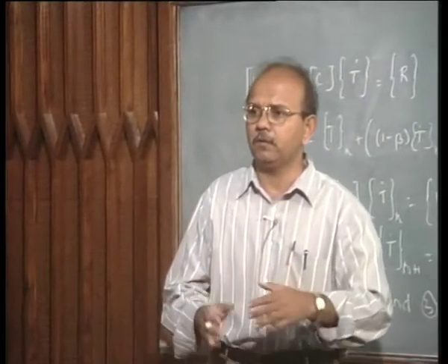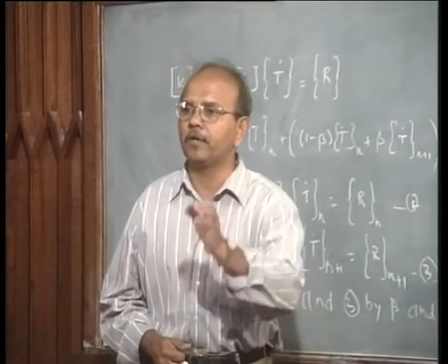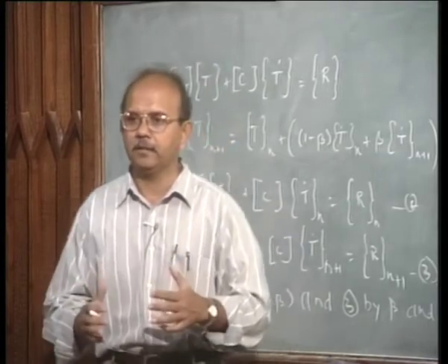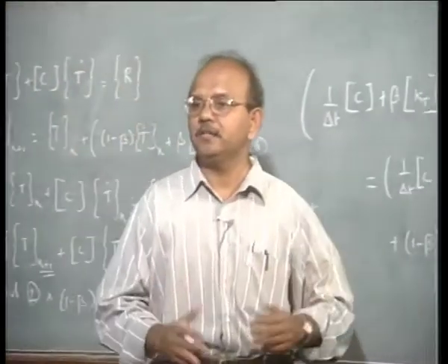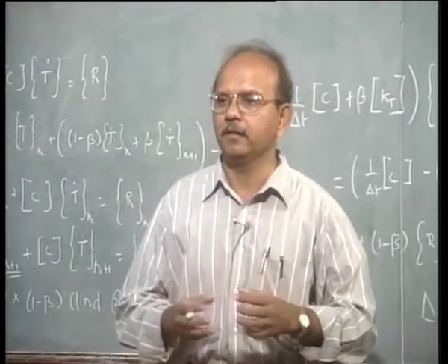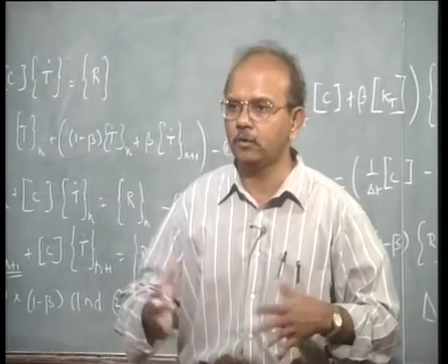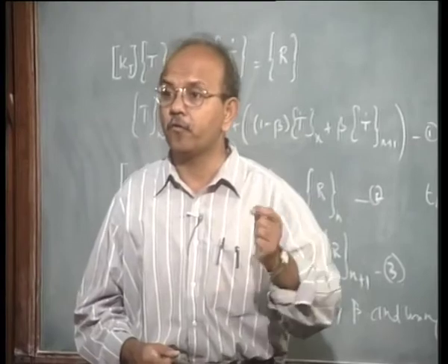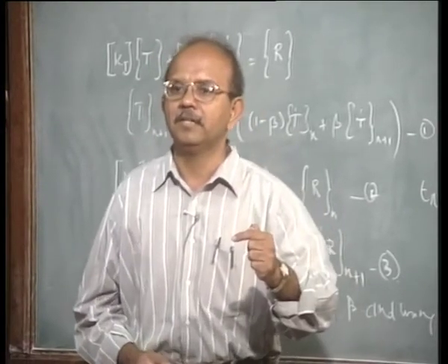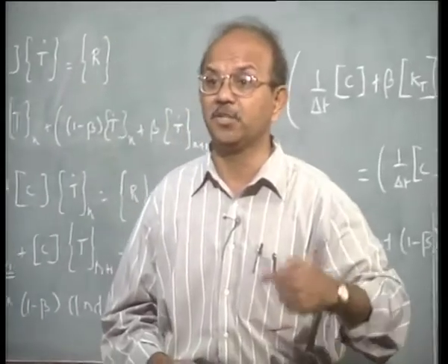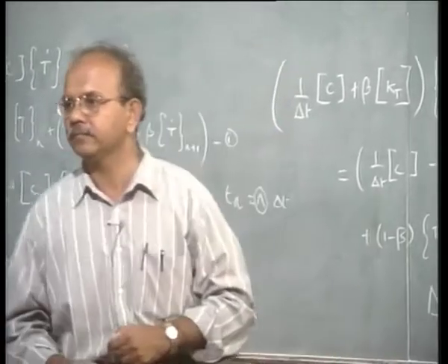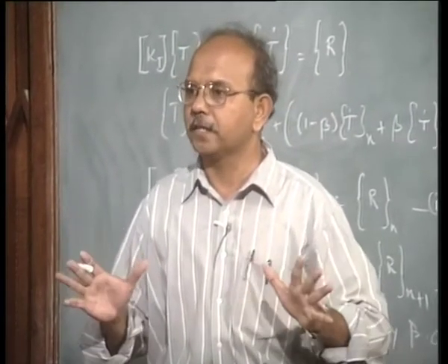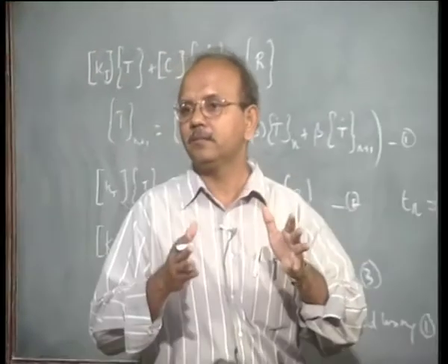We first solve the problem of temperatures at, say, t1, then stop there, and determine the displacement due to thermal expansion, if there is a load due to that. Then find out the stress and strain. So first the thermal problem, then the mechanics problem. Then again I go to the next step, t equal to t2, that is t1 plus delta t. Then again solve for the temperature problem. Is it clear? Then again look at the mechanics problem.